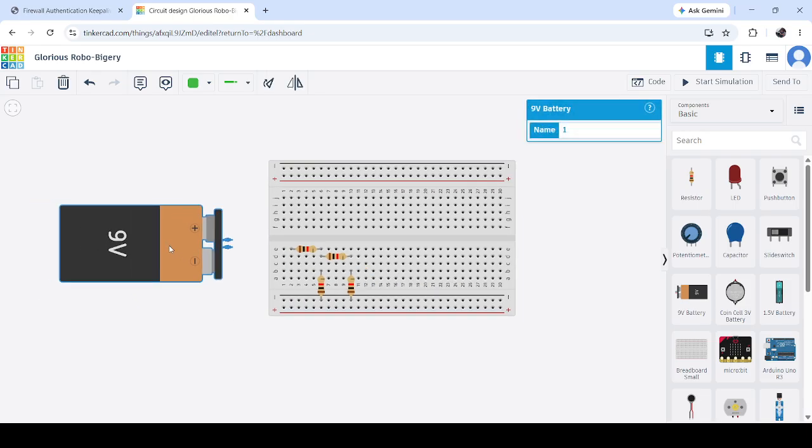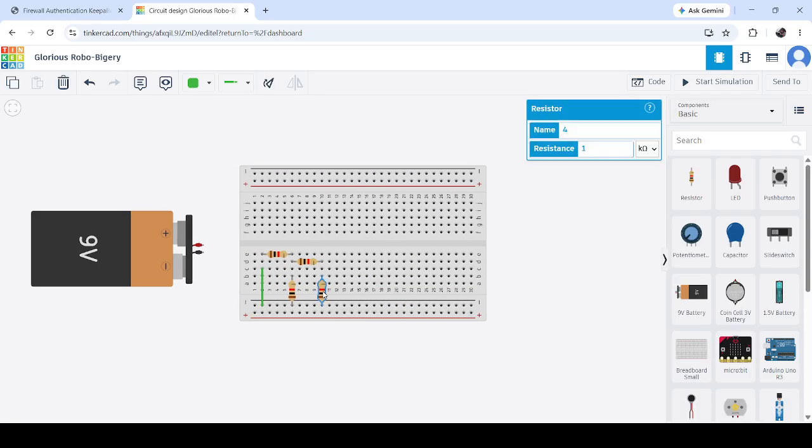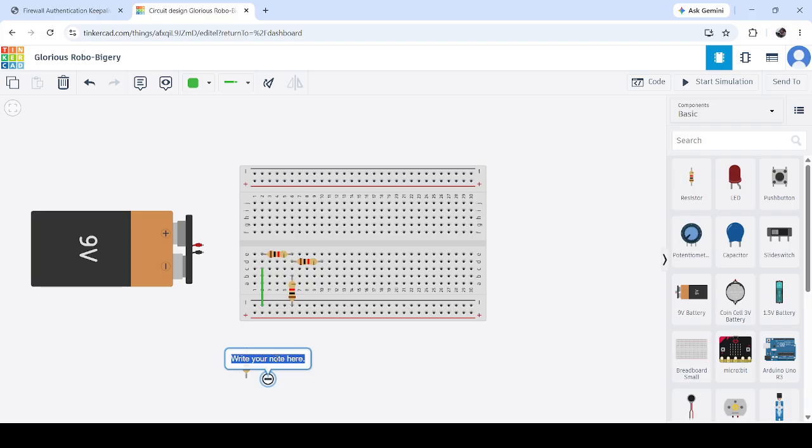Okay. So our first step will be to identify our Norton's resistance Rn. We will proceed as follows: if we have a voltage source, we keep it short circuited, and if we have a current source, we keep it open circuited. So in this case, I am short circuiting from here to here. Now we have the load resistance R4, which we have to keep outside, and we will mention it over there as our load resistance RL.